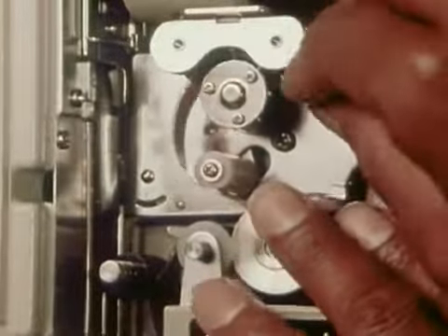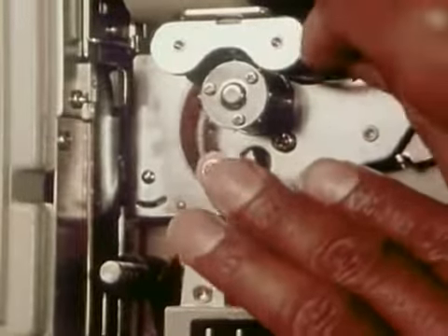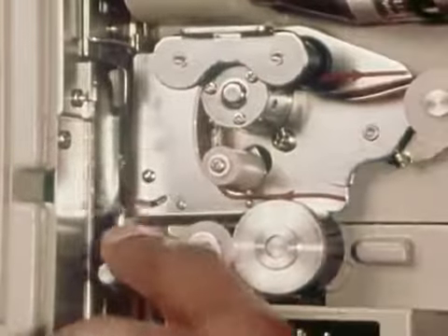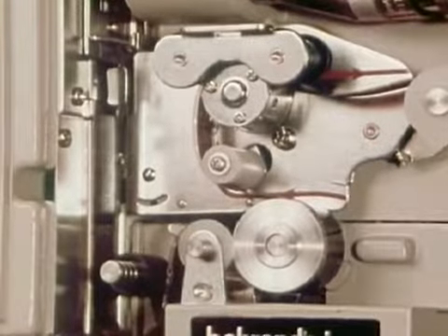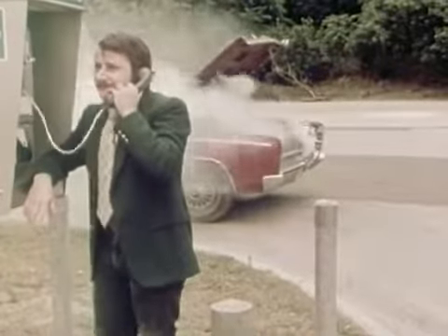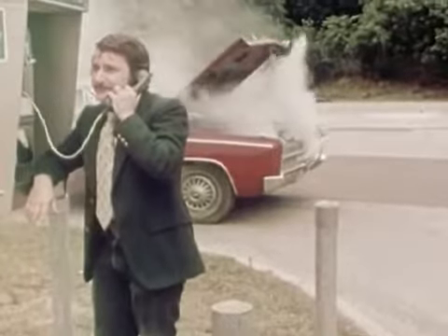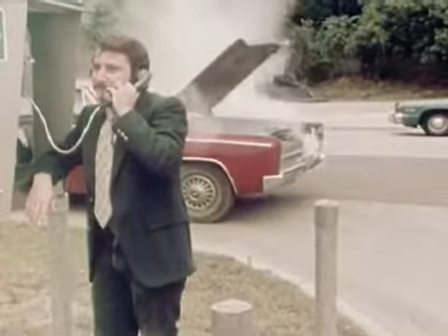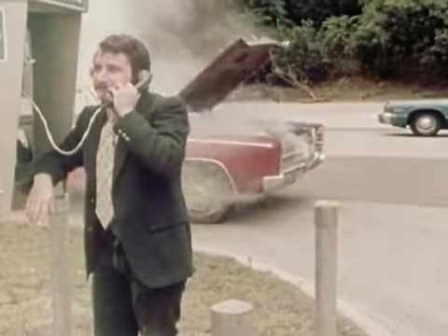The film must fit snugly over the sound drum, and the lower loop must always be the correct size in order for the sound to be synchronized with the picture. The sound is located ahead of the corresponding picture because of the distance between the sound section and the picture section of the projector. Properly threaded film appears like this on the screen.